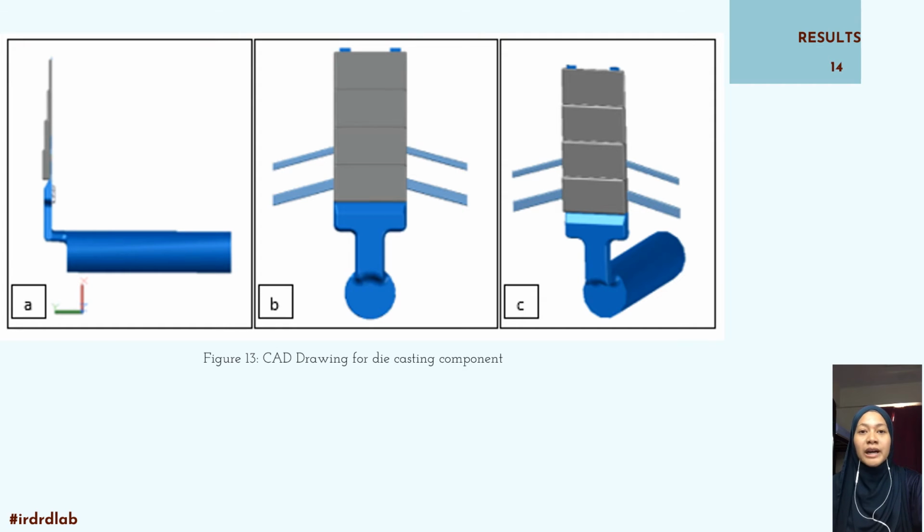Flow simulation parameters such as inlet velocity, original molten metal temperature, and pressure are used to observe the molten metal fluid flow. The figure shows the CAD drawing of the die casting system, which consists of the short sleeve, biscuit, runner gating system, and the cavity. The drawing as well as the dimensions of the cavity were received from Kyokuto Die Casting, Japan.